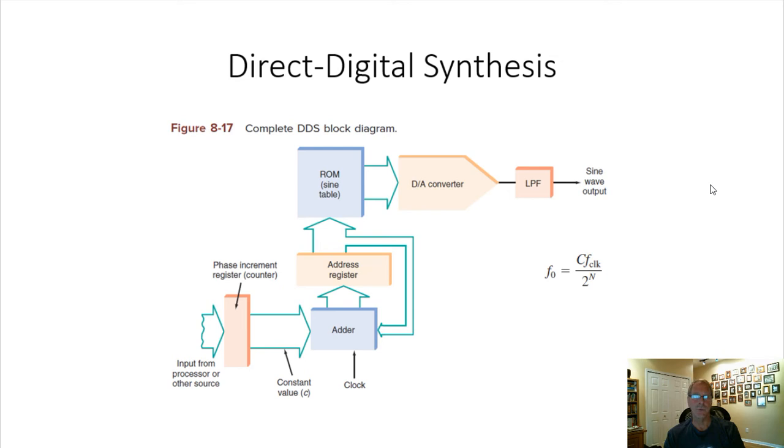And it can be adaptive pre-distortion, where at different frequencies, the antenna and transmitter system distort the wave differently. The microprocessor can know that and load the ROM table, in which case it would be a RAM table, random access memory, and change it differently and load it as necessary. And that would be adaptive pre-distortion.